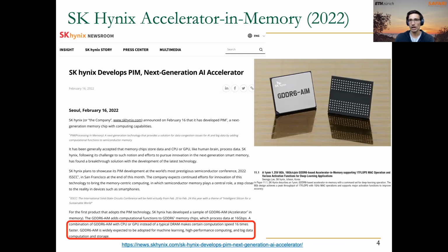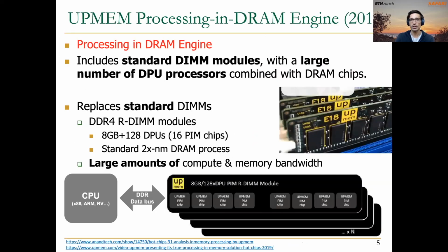Remember also this slide about the UPMEM architecture. Remember the UPMEM DIMMs, the PIM enabled DIMMs containing PIM chips. Inside each PIM chip we have memory arrays and small processors called DRAM processing units, or DPUs. We are going to talk in detail about these DRAM processing units today.